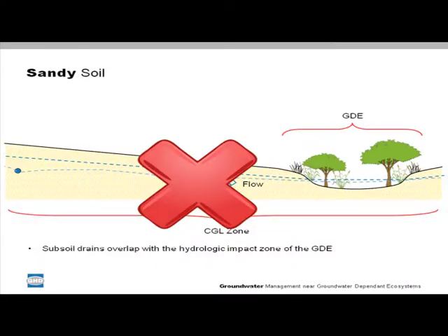Modelling recently undertaken by the Department of Water as part of the Murray Drainage and Water Management Plan suggests that controlling groundwater levels by 1 metre below ground level can alter a groundwater-dependent ecosystem up to 600 metres away. Therefore, an EWR investigation must be undertaken to determine a suitable controlled groundwater level and how close this can be to the groundwater-dependent ecosystem.